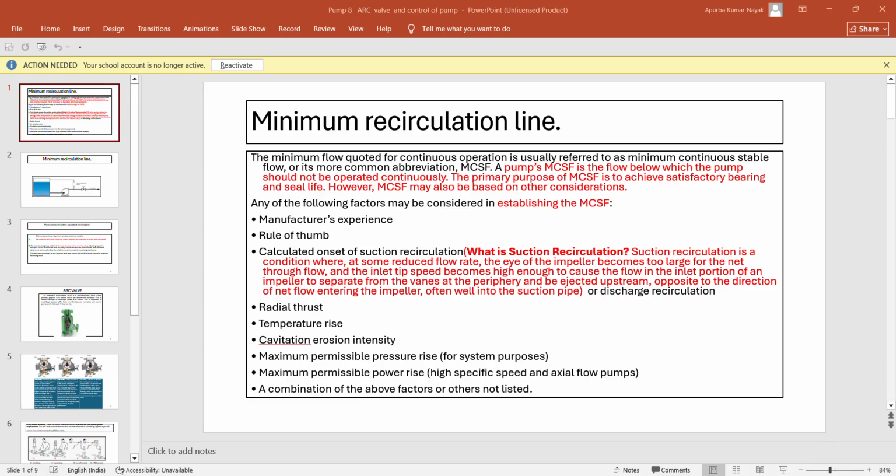Your pump is running. Your requirement is not there, so you can close the valve by this motor switch on and off. And this is the variable speed, that is also an instrument. With this you can increase and decrease the RPM of the motor like this, and with this we can control the discharge of the pump. These are the four ways we can run the pump.